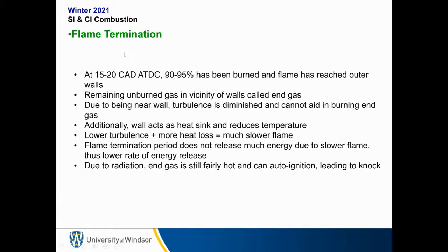Then we have the flame termination stage. At about 15 to 20 crank angle degrees after top dead center, 90 to 95% of the fuel has been burned and the flame has reached the outer walls. The remaining unburned gas in the vicinity of the walls is called the end gas.